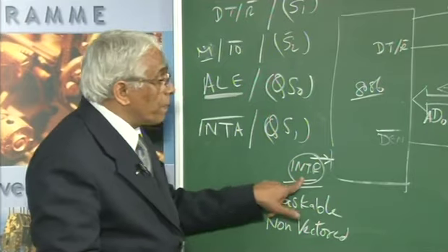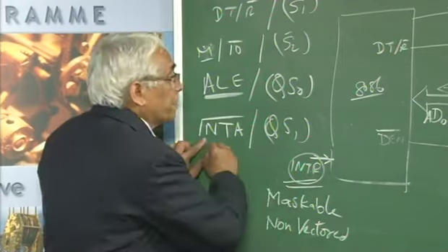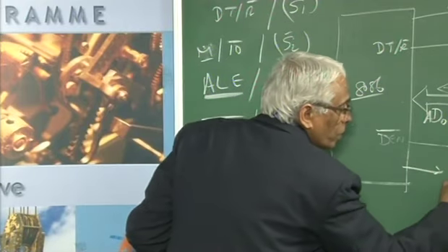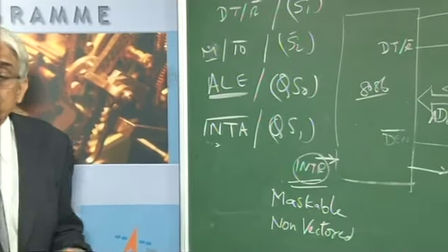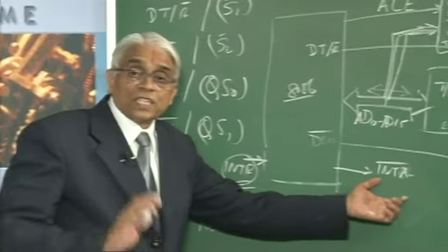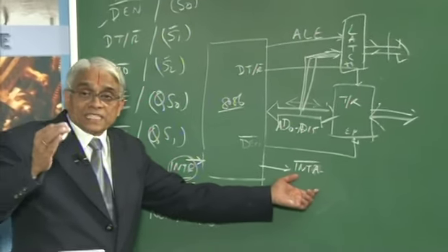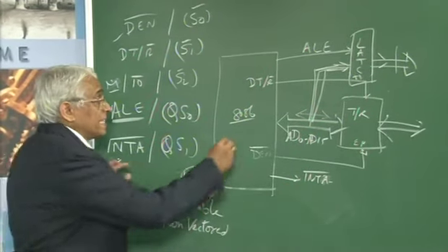So, the microprocessor sends an interrupt acknowledge signal to the external world, which is the signal used by the IO device to provide the interrupt type.